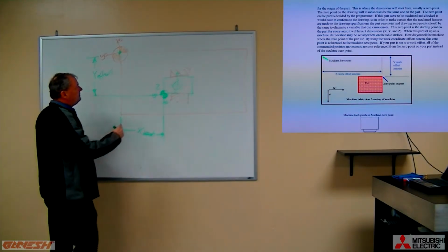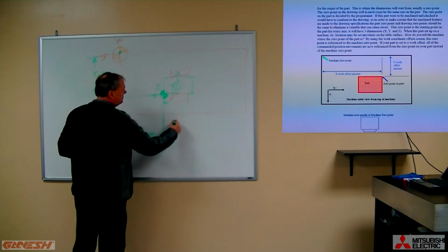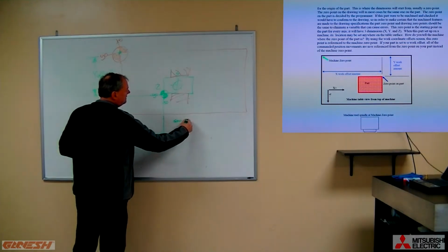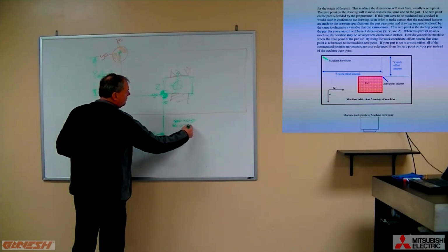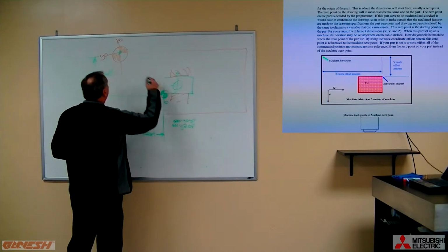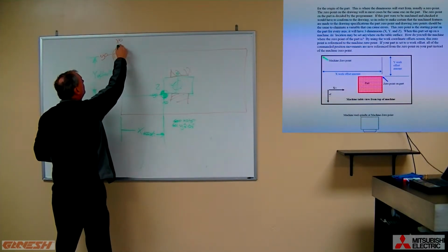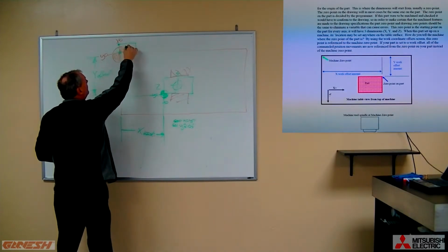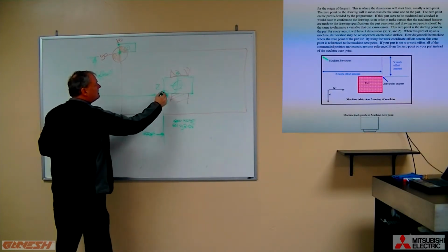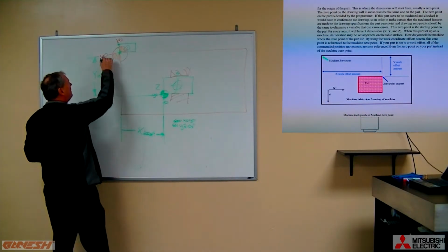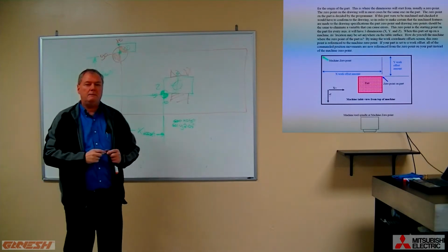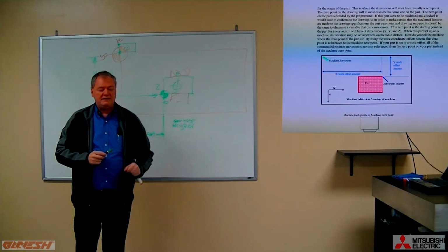And then if you say G00 X0 Y0, and then we tell the machine G01, make a move to Y2.0, it's going to go from this point and go 2.0 inches up, and it's going to actually try to machine your part up here, because you have not told it that your actual datum is shifted a given amount away from the machine datum. So two things happen.